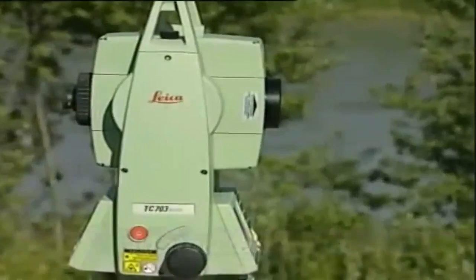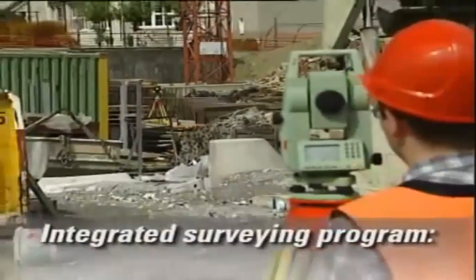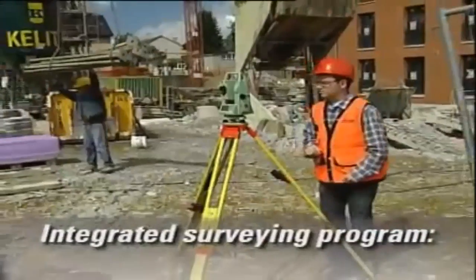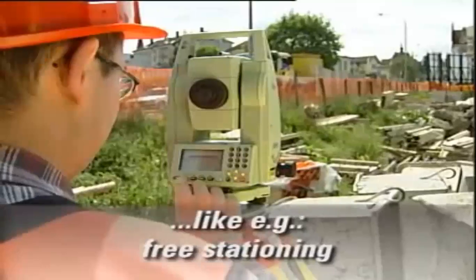Used with the integrated software, entire surveying processes can be automated. For example, with free stationing: set up the instrument in any desired spot and measure to 2 known points. Now, the TPS 700 computes the station's coordinates and performs the orientation of the instrument at a key press.